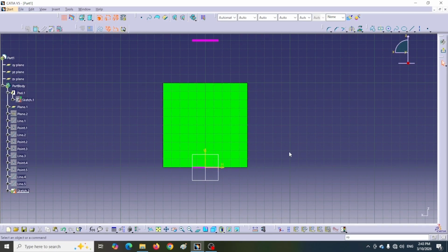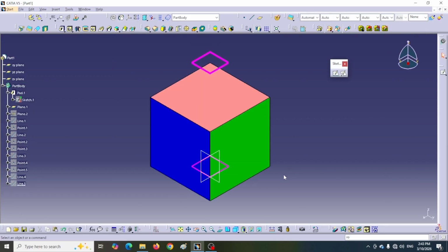So far, when we selected a plane to go to the sketch environment, we had to use the coordinate axis of that plane. This means that the plane already has its own center and coordinate axis. But what should we do if we want to have a plane with a specific center and axis? Here we use a tool called Positioned Sketch to define a dedicated plane. With this tool we define a flat surface, center and axis with their direction.